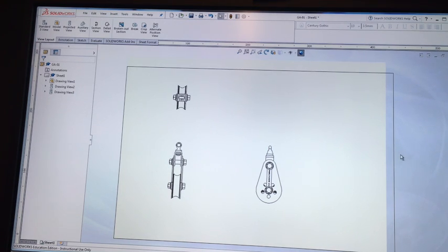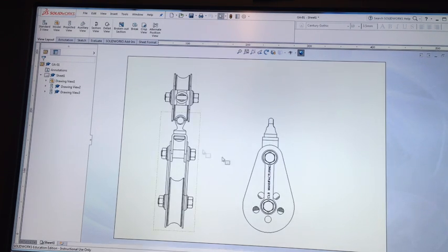First thing, when you import a drawing view, the first view to the page, SolidWorks will rescale your sheet format to suit. So if you picked another part, like a smaller part, it might have made the part a different scale. So even though this sheet would have started at 1 to 1, it's now 1 to 2. You can see that in the bottom right of the screen. If you click on that, change it to 1 to 1, and to get everything up to 1 to 1 size.